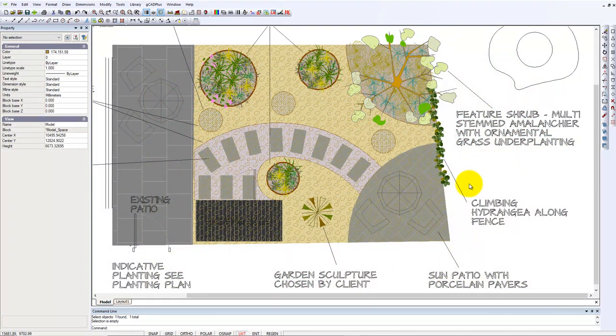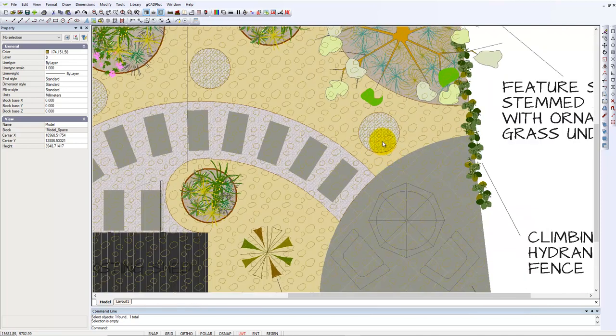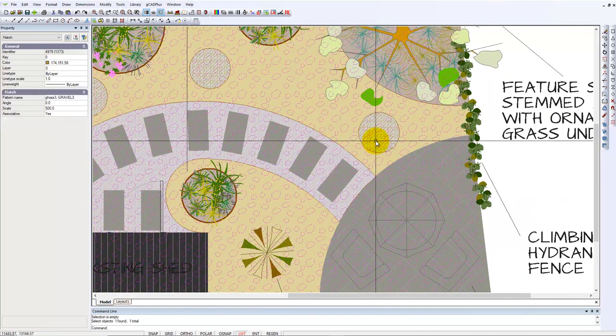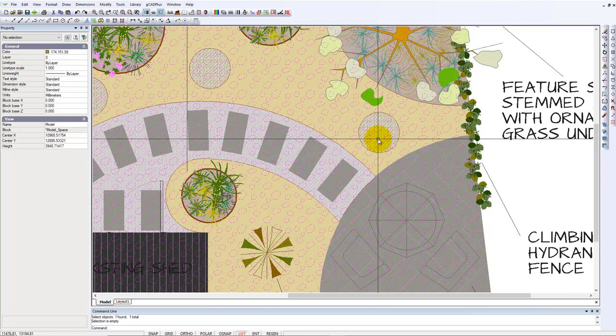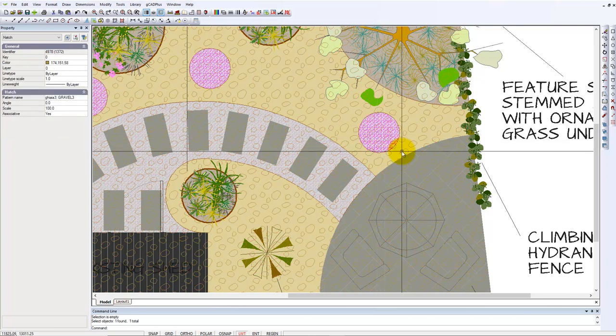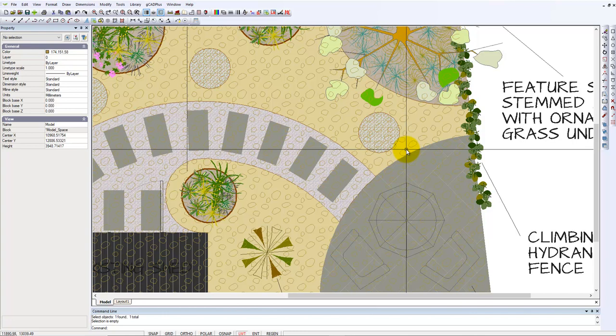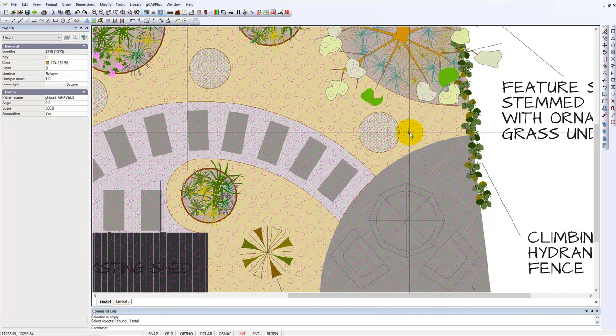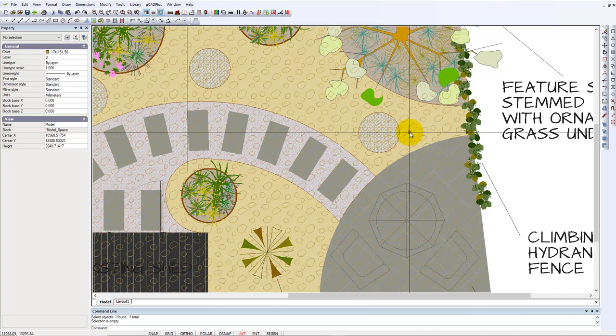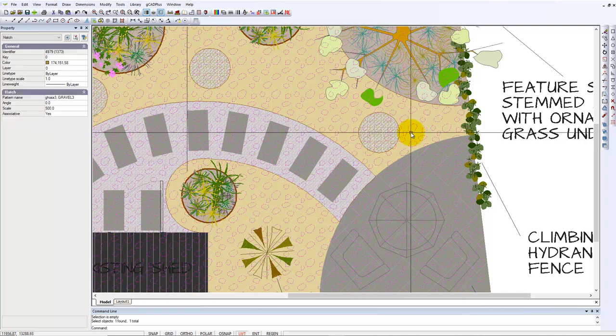Well, we don't have a tool in gCADPlus that will enable us to take that internal hatching from those 3 hatched circles and shuffle the order and move it in relation to the coarser hatching so that we get the right sort of effect. Because hatching is one single entity. It doesn't have within it opaqueness. We do have a solid hatch, but I digress.